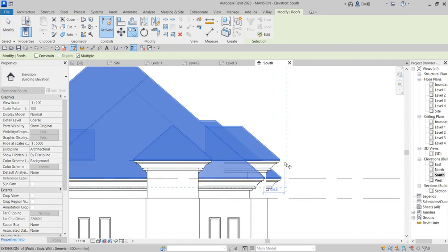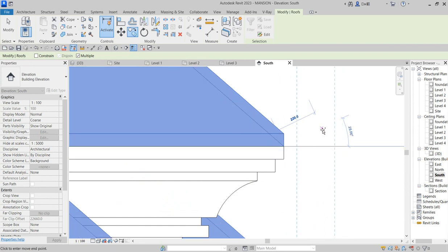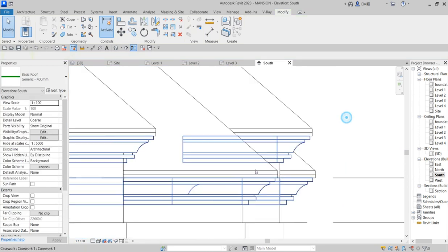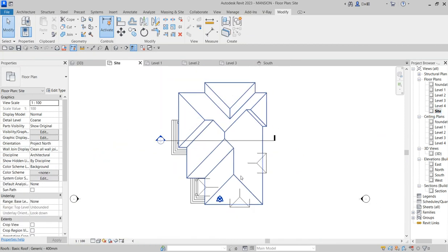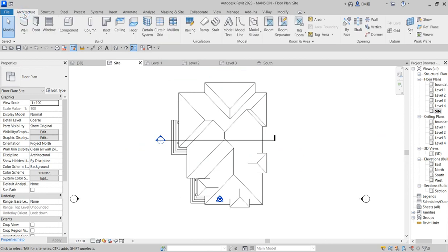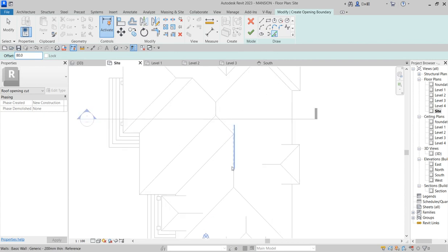then you say copy from here. Just one step of copy and everything is in order. So you do that. So when you go back and you go to your sites where you are seeing the full plane reference of the roof, you click on architecture and you come to vertical, you select the main roof, because that's what we want to do. So you pick up this, then you offset from here, say 80.